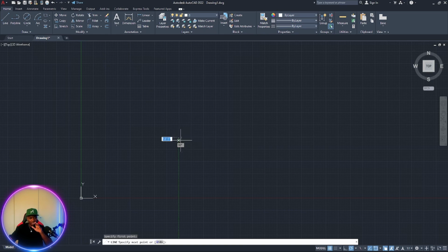This is the start. We go along and make sure that your snapping tool is indicating the green line and the angle is on 0 degrees, or depending on the direction, 90 degrees. I'm going to the right and making sure it's snapped.